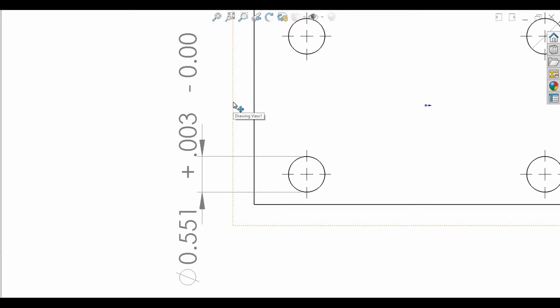Now, the way to visualize that in your head is imagine a ruler that only has tick marks on the 1/8 of an inch, and you're trying to measure a long plank of wood with it. So if the end of the plank of wood ends up in between an 1/8 of an inch tick mark, then the accuracy is limited to only where those tick marks are. Any measurement that falls between the tick marks is going to be in that error range, plus or minus an 1/8. And that's really all we're saying here, is plus or minus a small amount of deviation from it.